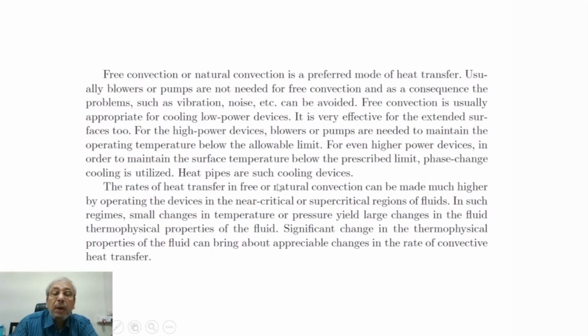We will come to know about heat pipes in this course later. The rates of heat transfer in free or natural convection can be made much higher by operating the devices in the near critical or supercritical regions of fluids. In such regimes, small changes in temperature or pressure yield large changes in the fluid thermophysical properties.